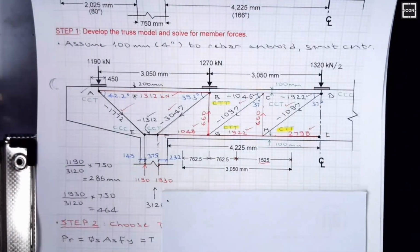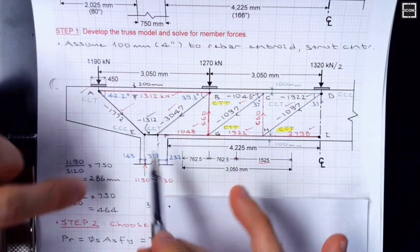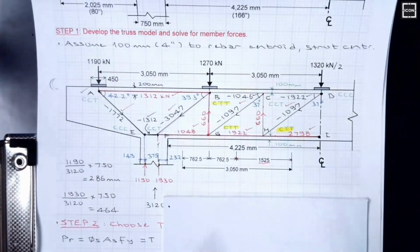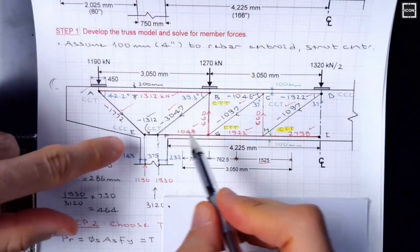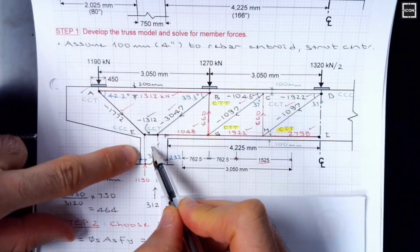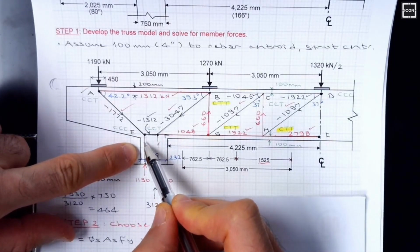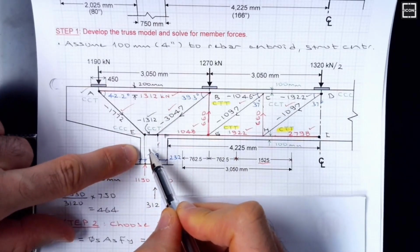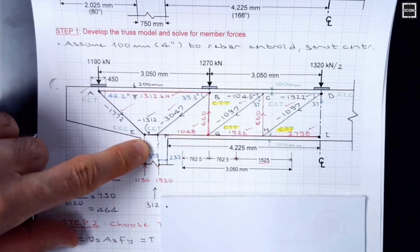I got a question. It was a very good question. The participant is asking how we size the column, how we determine the nodes. So my explanation was because of three reasons. The first reason, you would like to use your column efficiently, which means that you allocate a certain distance for each strut. So if the force is low, you allocate a smaller distance. If the force is high, you allocate a larger distance. So that is my first explanation.